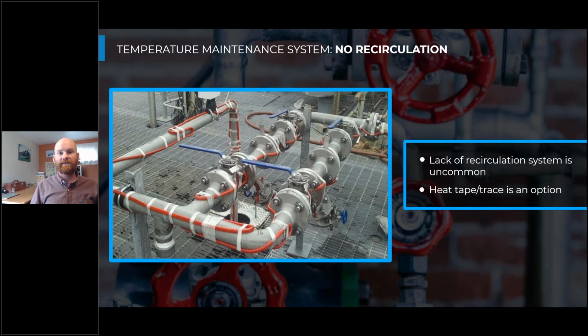But if you're maybe serving 3 to 4 units and you have access to that hot water piping that's serving those 3 to 4 units, this may be a really low first cost option, but will result in pretty poor performance because this electric resistance heat tracer tape is operating at a COP of 1 or less than 1, whereas our heat pumps or our swing tank is operating at a COP of closer to 2 or above if we're sizing that swing tank appropriately and we're having multi-pass heat pump on that dedicated parallel example.